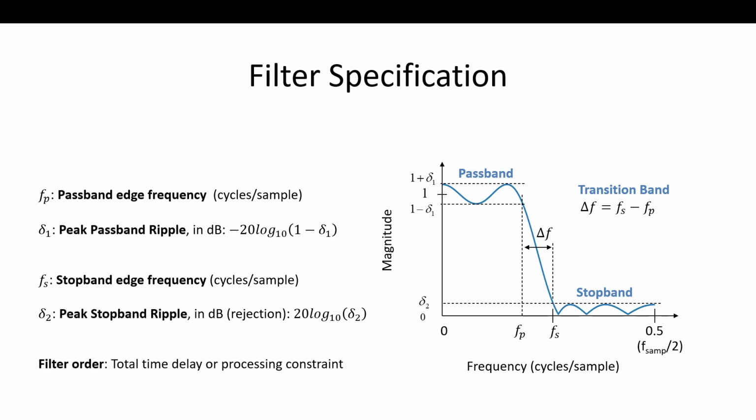I'm not mentioning it here, but I do want to mention that because I'm talking about linear phase filters, the phase is linear. It just keeps increasing as you go up in frequency at a linear rate, just like any delay line would. That's just a subset of filters, the one we're talking about today.